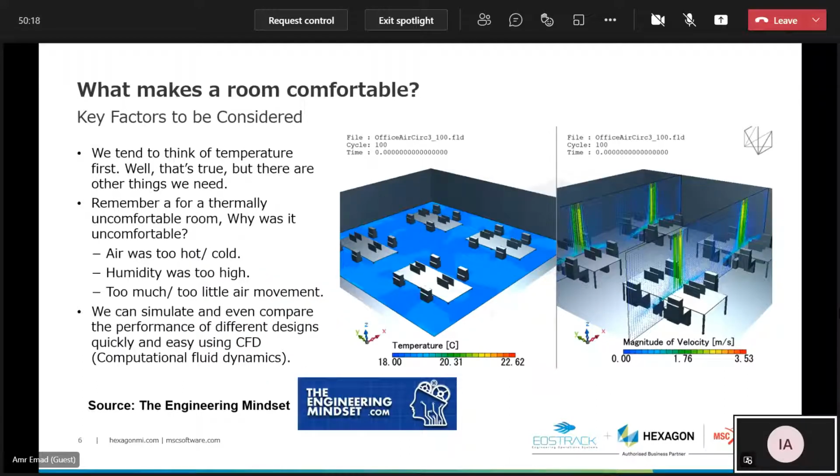So, not to be long, in order to handle such issues, for example, we have four vents here, and the velocity that the people sitting there will feel is around 1.8 meters per second. This may not be according to the standards and the statistics gathered from different people in different countries. This value is not suitable and will make you uncomfortable. So this factor should be considered, and the people sitting here will not feel comfortable anyway. So we have to handle this.